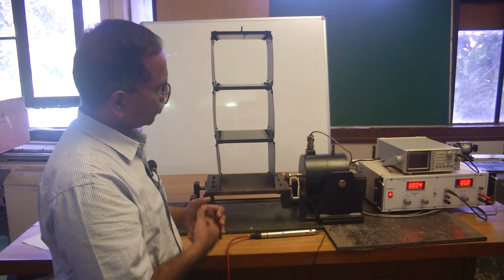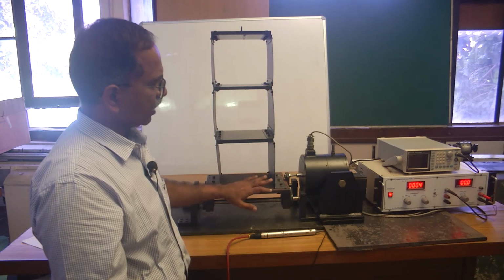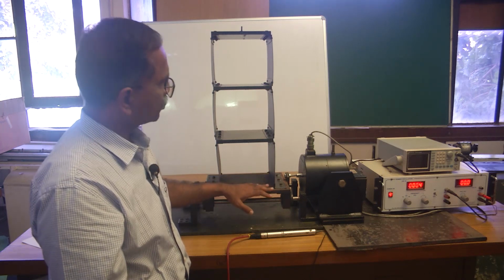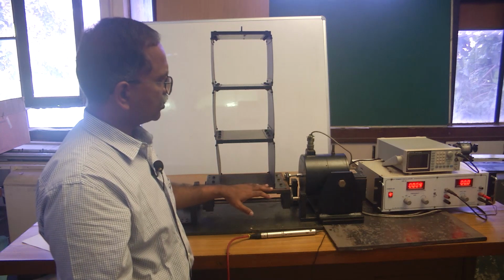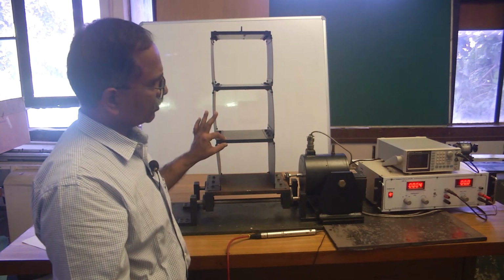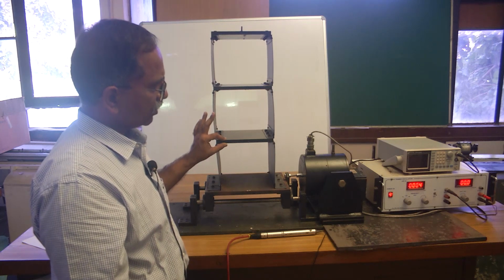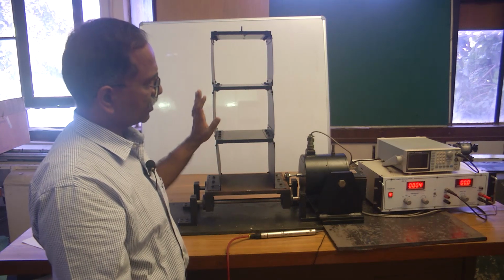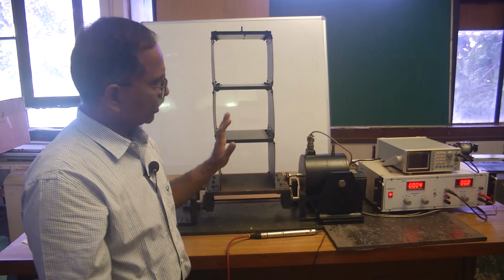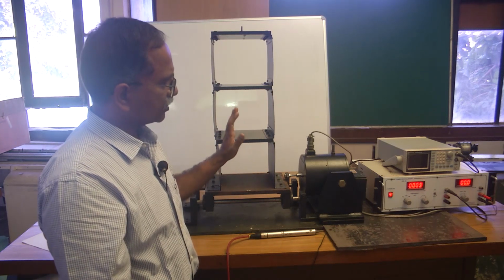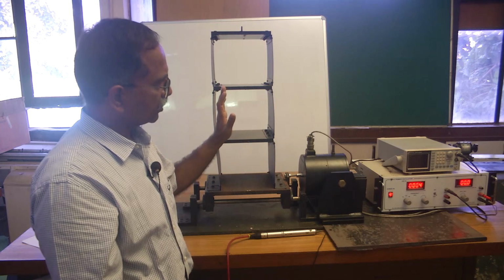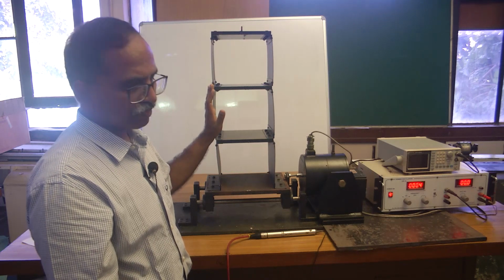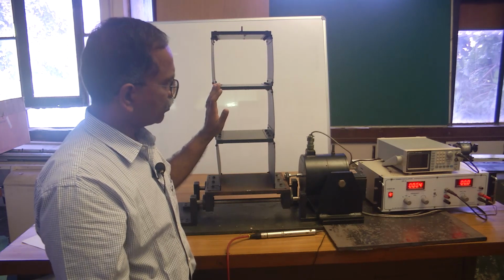And therefore, what we are going to do is excite this at a frequency matching maybe the first, the second and the third natural frequency. When we are exciting this vibratory system at its first, second or third natural frequency, the frequency corresponding to the principal modes of vibration, we expect this entire vibratory system to respond at resonance, and the displacement pattern that we will observe at the resonant condition will conform to the mode shape corresponding to that particular principal mode of vibration.